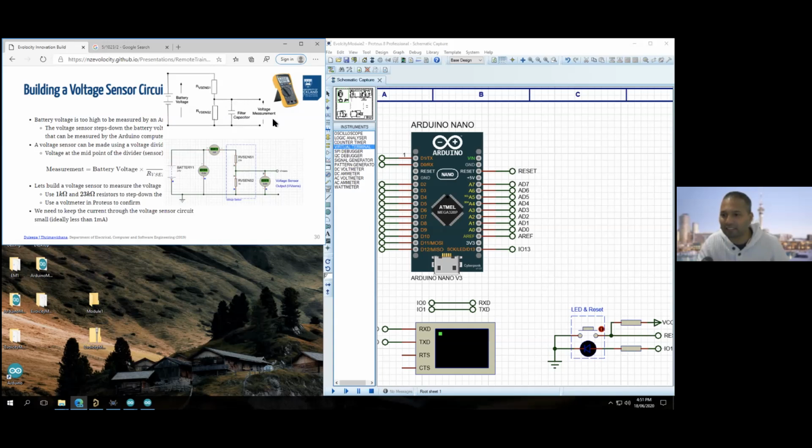No, that's the point. Before you go back to the example I said, I was talking about 5 volts there, but if they're both identical, then you lose half the energy in each of them. So going through the first one, you lose 2.5 volts. Going through the second one, you lose 2.5 volts. Going through both of them, you lose the whole of the 5 volts. You happy with that?